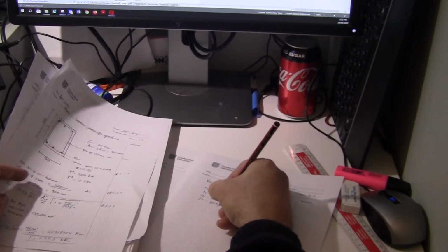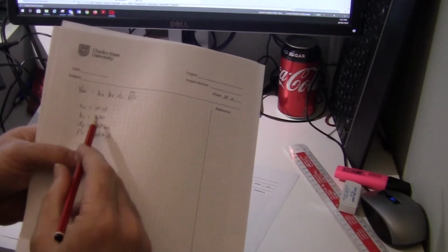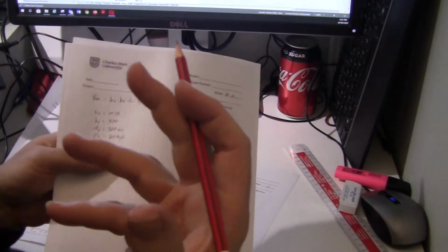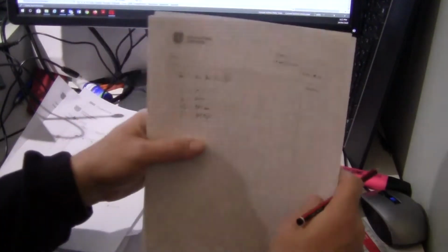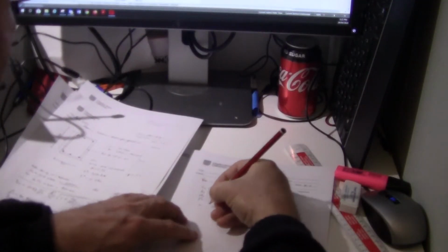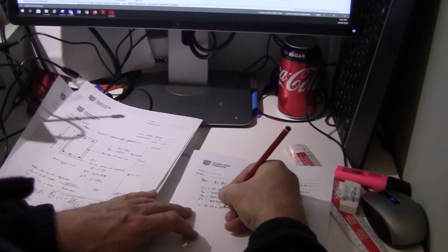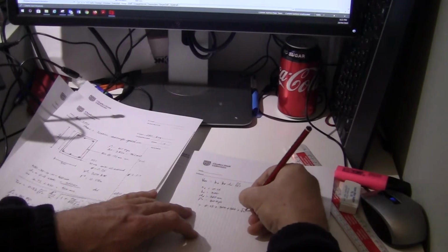All right. So look at those terms. There's a constant. There's the area of the beam if you multiply it by those two, and there's the concrete. This is the shear capacity of concrete. So it's no surprise that the steel doesn't come into it. Let's multiply that out. We get 0.15 times 300 times 360 times the square root of 40.